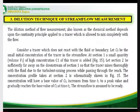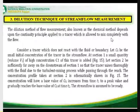At section 1, a small volume V1 of high concentration C1 of this tracer is added, figure 15. Let section 2 be sufficiently far away downstream of section 1 so that the tracer mixes thoroughly with the fluid due to the turbulent mixing process while passing through the reach. The concentration profile taken at section 2 is schematically shown in figure 15. The concentration, at a base value of C0, increases from time t1 to a peak value and gradually reaches the base value of C0 at time t2. The stream flow is assumed to be steady.